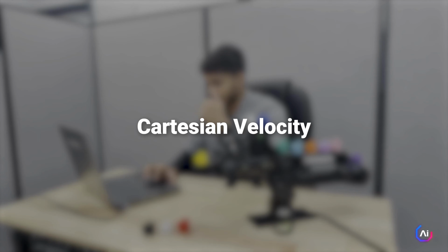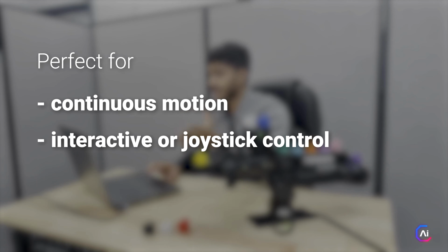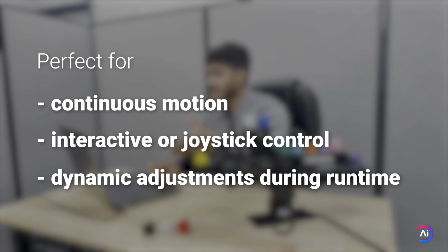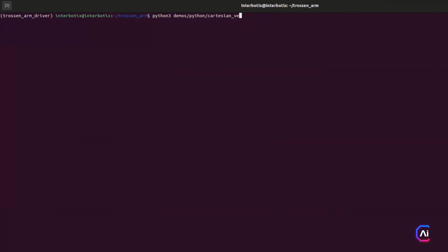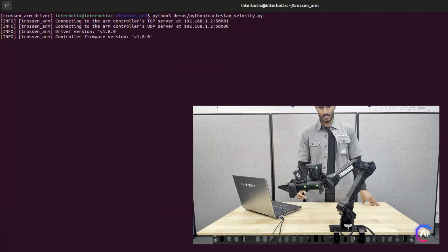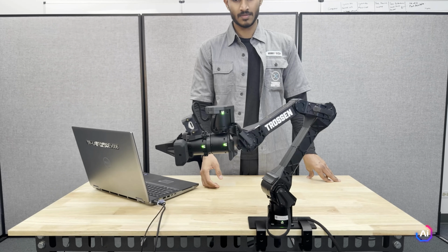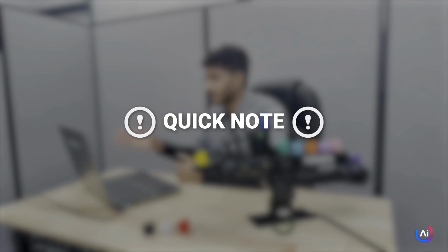The Cartesian velocity. This mode allows you to glide the end effector in a direction with a specified velocity vector. This is perfect for continuous motion, interactive or joystick control, and dynamic adjustments during runtime. In this demo, we use the Cartesian velocity control to simulate a spring mass damper system, also known as admittance control. The arm reacts to external forces by updating the velocity in real time, making it behave like it's attached to a virtual spring. Just a quick note, this is a toy example. The gains used here are for demonstration only.